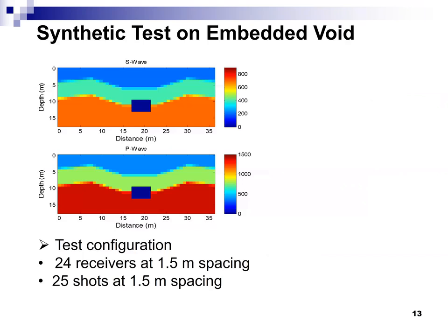May I ask, in terms of a source at the surface, if you could deal with a single frequency at a time, you would be solving each one of those separately. That's frequency domain. Yeah, we do both. Later on, we'll talk about frequency domain inversion in 3D. Here we do time domain, because in time domain we have a consistent magnitude. Initially, we did frequency domain, but the magnitude of the waveform generated from the sledgehammer is not consistent. We have peaks and troughs everywhere, so we cannot select a consistent component to do inversion. So time domain helps.